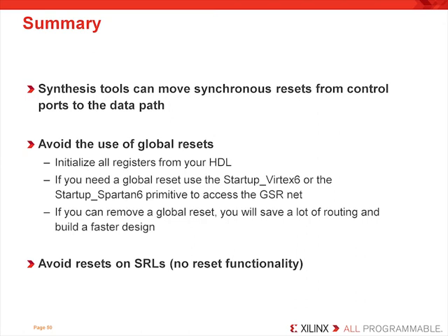And again, avoid resets on your shift register LUTs, specifically here since the shift register LUT has no reset functionality, unlike the DSP slice and the block RAM, which do have reset capability. So keep that in mind. If you can avoid using resets in your design, you're more likely to get many more shift register LUTs.